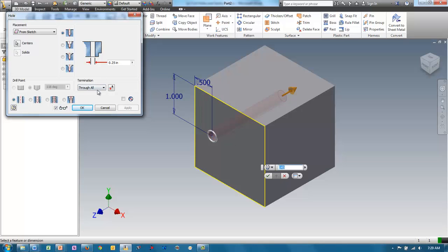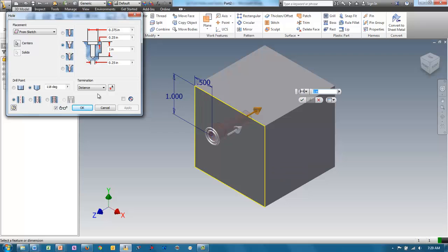So the first thing I'm going to do is I think I'm going to do a blind hole, and it's going to be a counterbore. And remember, a counterbore allows you to recess a screw head under the surface of the material. So I'm going to just take a look at the defaults here. So this is 3/8 of an inch, 0.375 width for the top. So that would be the head of the screw. It's a 1/4 inch deep, so it'll accommodate a screw head of that size.